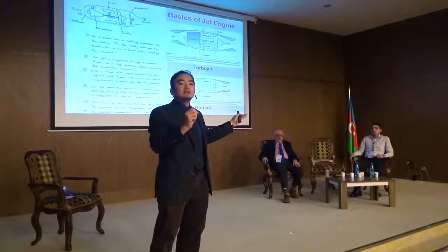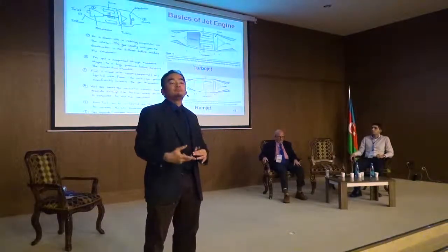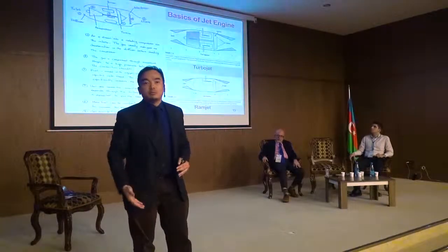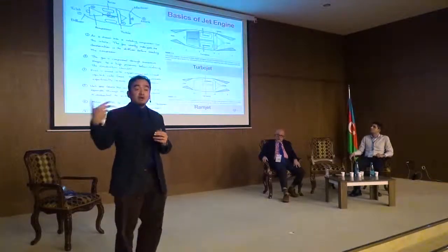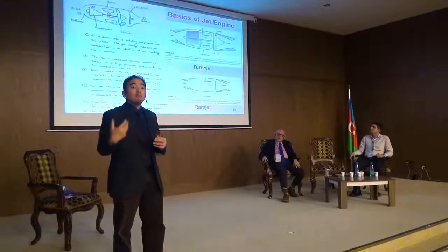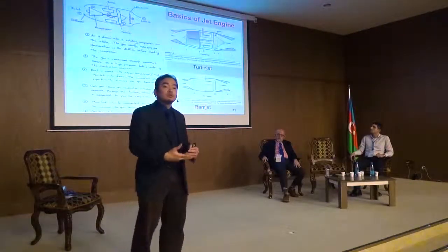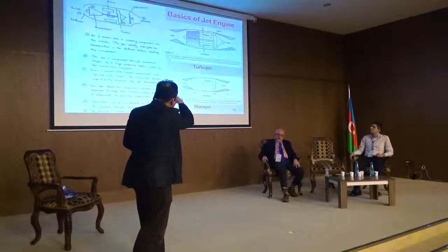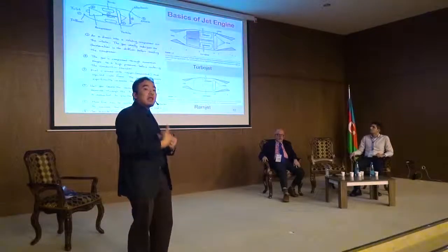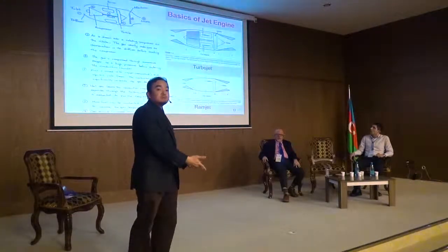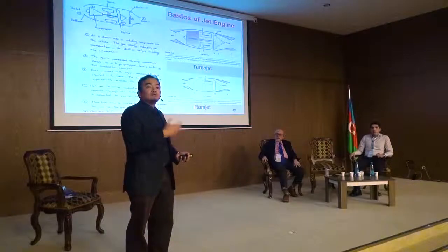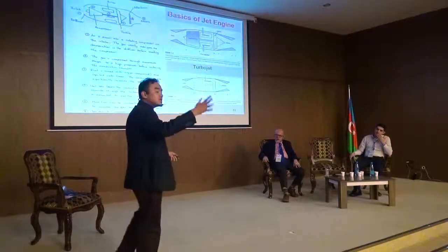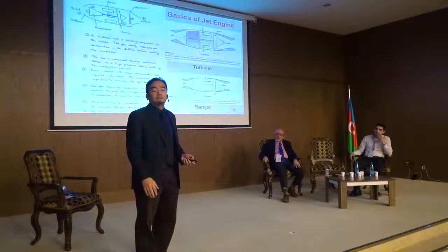This can only be done if you have a highly supersonic flow, hypersonic for example, where with a very high speed flow, the compressibility is increased. So the air is basically compressed by itself. The design of the jet engine allows this compression to take place even without a physical compressor. Then you inject the fuel, and it is ignited by itself.